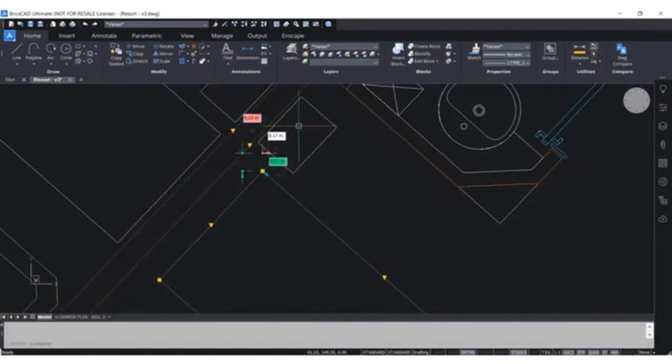Here I would change the overall distance to 3.5 centimeters, so that the bed gets moved closer to the wall. This workflow replaces having to recall any distance, running the command move, selecting points, and eventually toggling between your snap options, or turning your ortho on and off. Just select 2 entities and key in the value.